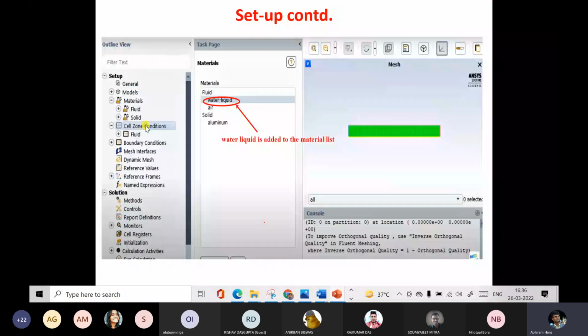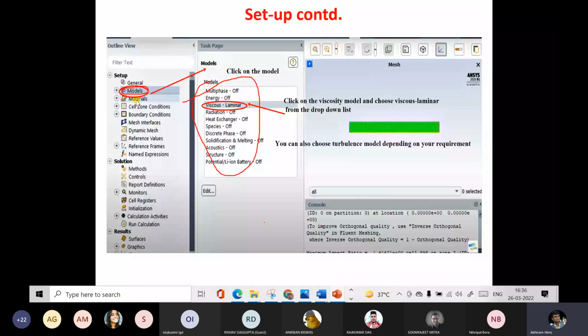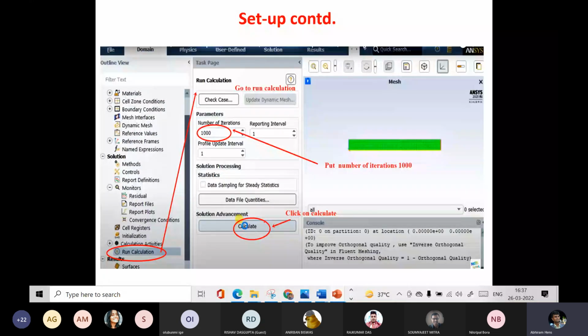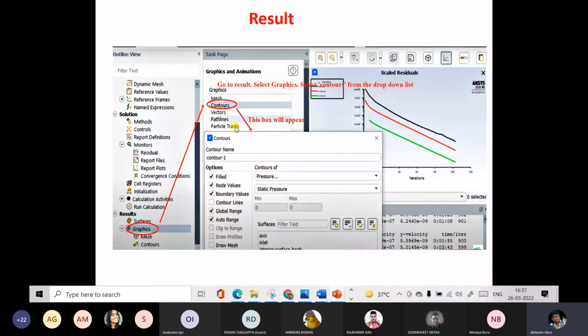Okay, this viscous laminar part. So the moment you declare viscous laminar, you are basically defining the equation here. Now, if you don't have knowledge about the Navier-Stokes equation, you cannot understand what equation it is taking. Obviously, you can get the details from the Fluent manual. You can get the details of these viscous laminar equations, from where you can relate to the Navier-Stokes equation.